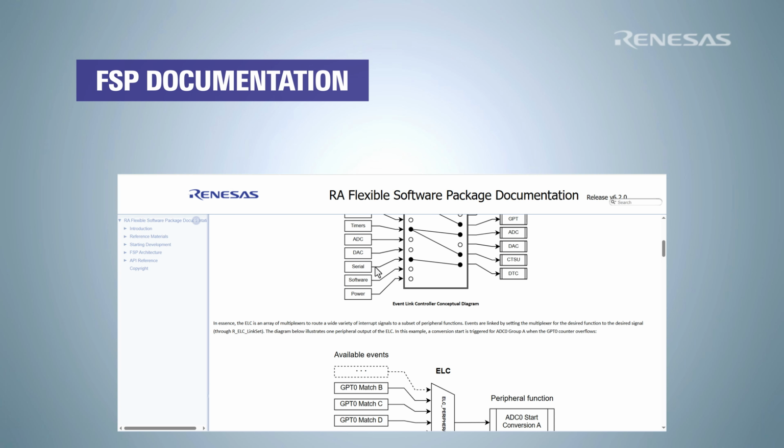In this project, we will demonstrate both approaches. First, we will trigger an ADC conversion on a timer overflow without using the ELC. After that, we will use the ELC to start the ADC conversion automatically when the timer overflow occurs.